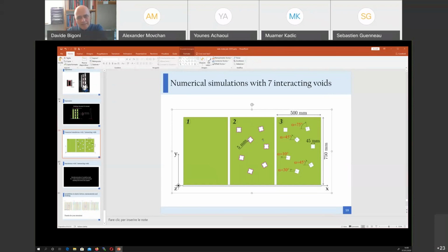By the way, the experimental verification of in-plane waves is very complicated, more than flexural waves, because for flexural waves we have used stroboscopic light and fast recording. But for in-plane waves, you should use other things, for instance a laser scanner or something like that. So it's more complicated, but I think it should work.